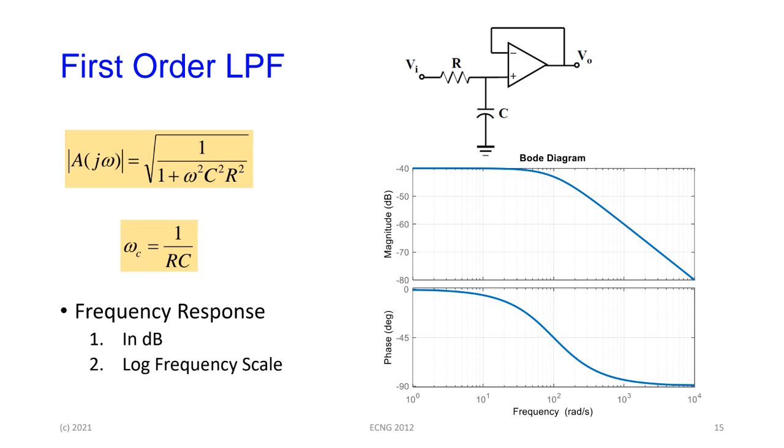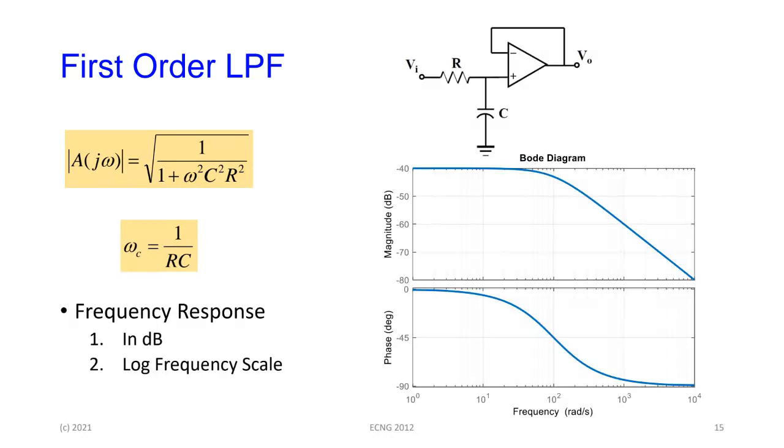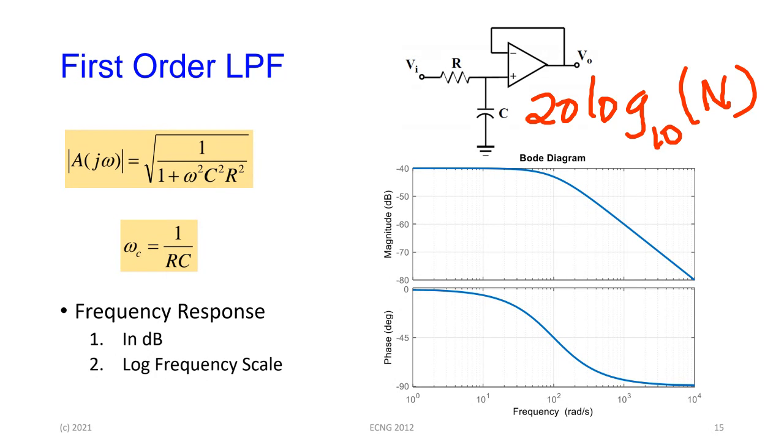Ask any questions. So what we normally do, though, instead of using a magnitude plot like we have here, is to use a logarithmic plot. In the log plot, we plot the magnitude of the response in decibels, and we also use a log scale for the frequency. Now, first off, in decibels, again, you would have met this before. To convert a number from a value into decibels, it is 20 log to the base 10 of the number. Usually decibels are a ratio, supposed to be a ratio to some standard, but here you could consider it a ratio of something to 1, for argument's sake. It is 20 log base 10, remember that.